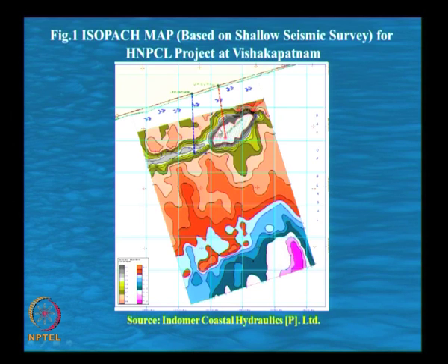One of the pieces of information you can get is when you have a submerged outcrop. See, this is for a seawater intake and outfall system. This is a landfall point, called LFP, landfall point for the seawater intake. This is the place where we get the water from. At this location the water depth may be about 11 meter or so.